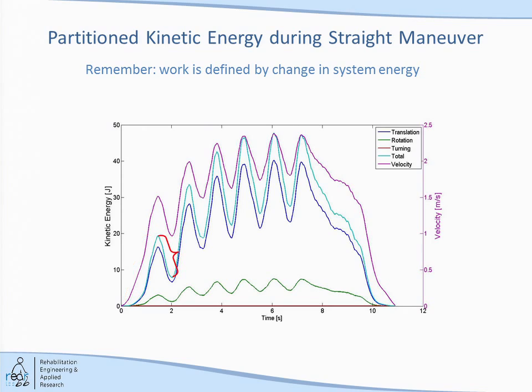But then what happens? You lose energy. And this is the problem with wheelchair propulsion. It's highly inefficient because every time you do work into the system, there's this moment of time when it gets sucked out of you and taken away. And this is resistive energy loss. This is what happens when you release your hand from the hand rim, because no torque can be applied and you slow down.